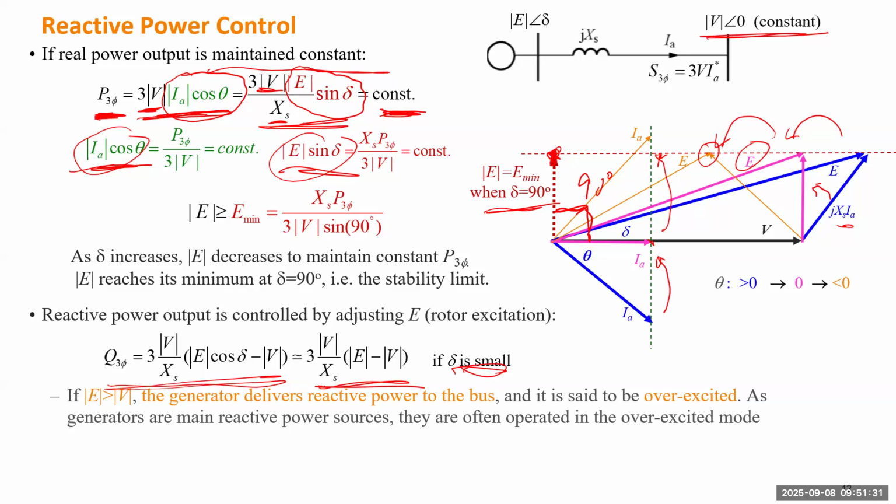So in a practical power system, most of the loads actually have internal reactance. As long as they have some inductance, they will behave as some reactance and will consume some reactive power. And the overall complex power consumed by the transmission line also has positive reactive power. We mentioned the transmission line is also a reactive load. So finally, the only reactive sources in the power system will be generators and some capacitors.